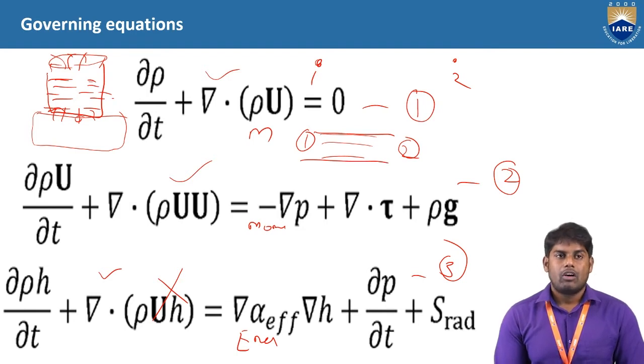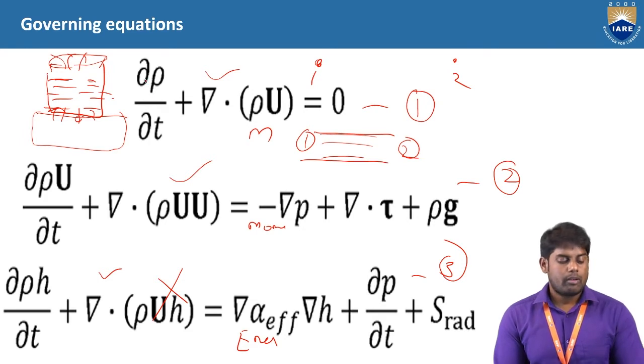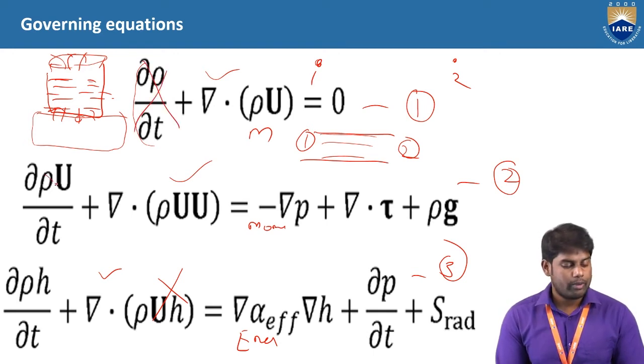So if you have only incompressible flow, where there is no change of temperature, or where temperature effects are not that predominant, then the continuity equation and momentum equation would be enough to calculate these flow properties. If the flow is incompressible, then this term will be zero, so the density term will also be negligible. The variables will be, for a simple problem, pressure and velocity.